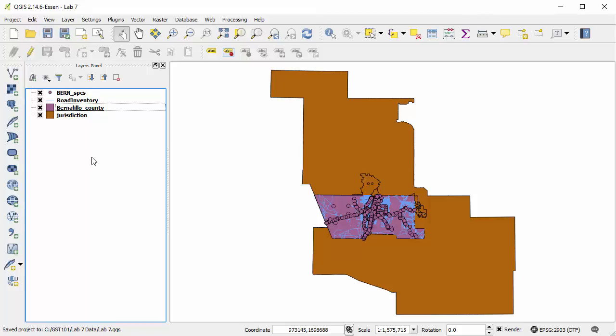So we're going to want to filter the monuments, so we only have the ones with orders and classes that we're interested in. So we only want monuments to meet the following requirements. Elevation order is 1, last recovered on or after 1995. Satellite observations were used for monument coordinate determination. So, what I just said: elevation order is stored in the attribute field elev order. Last recovered is stored in last recv. And satellite observations is stored in sat use.